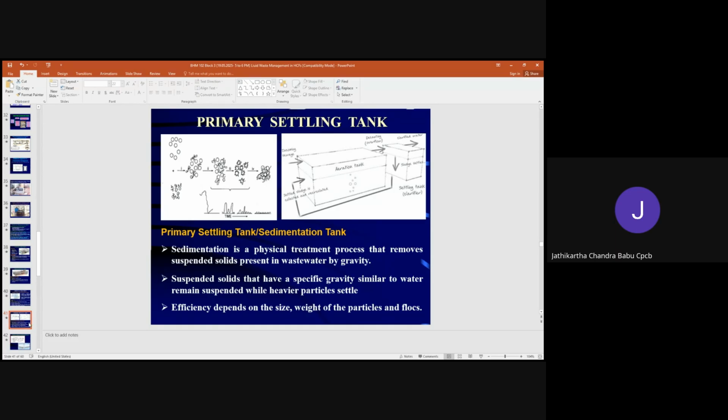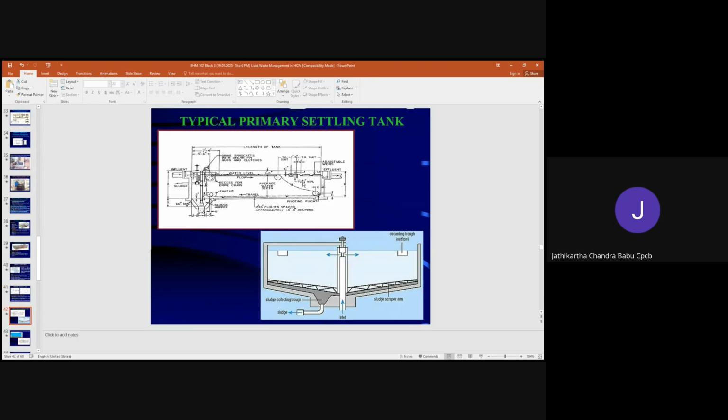Here also, in the aerobic process, the activated sludge process, diffused air is applied, and whatever flocks are there in floating form will all settle and come into the oxygen process. The size will grow, and when it goes to the settling tanks, we call them clarifiers. When the wastewater is sent to these clarifiers, slow mixing takes place.